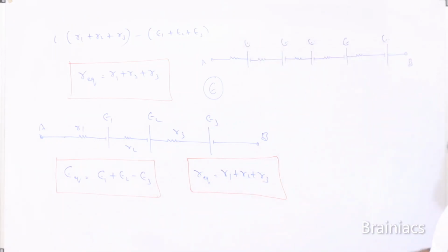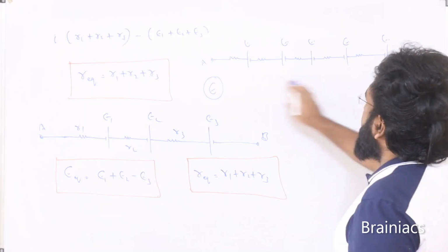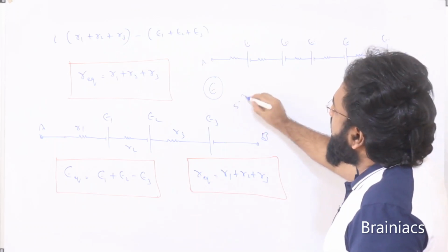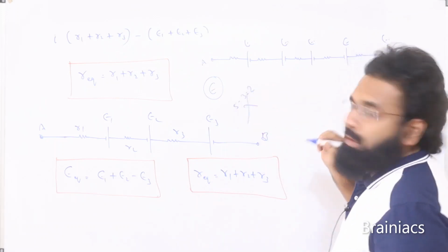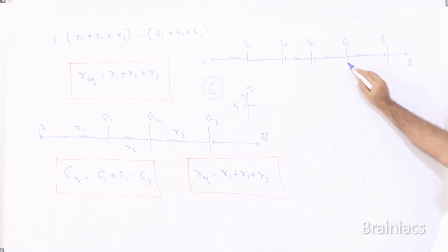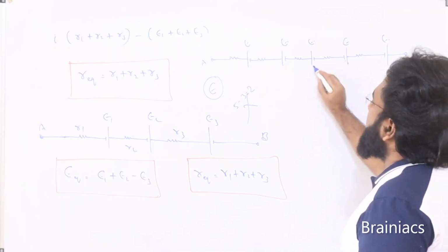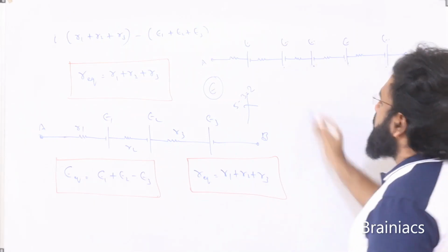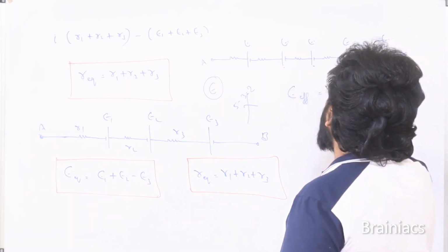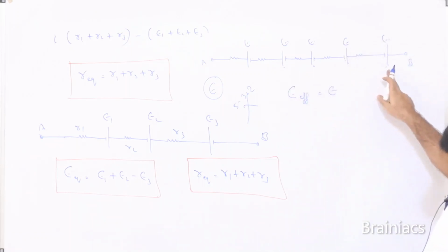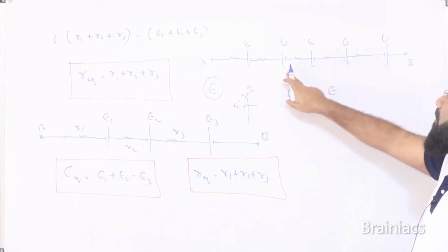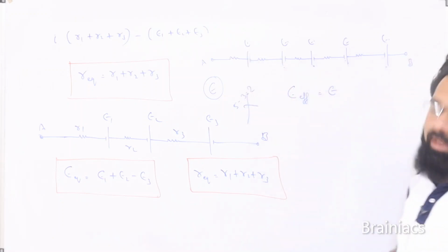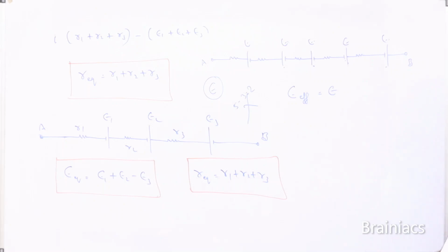Now what will be the effective EMF? If we think like total is 5, 2 are reversed, and try to write 5 minus 3 is equal to 2, this is wrong. See, this EMF will cancel the EMF effect of this one, and this will cancel the EMF effect of this one. So the effective EMF is going to be just E. These two will nullify the effect of 2, then remaining only 1 will be there. So this is how we should handle them. Okay, we will do some problems.